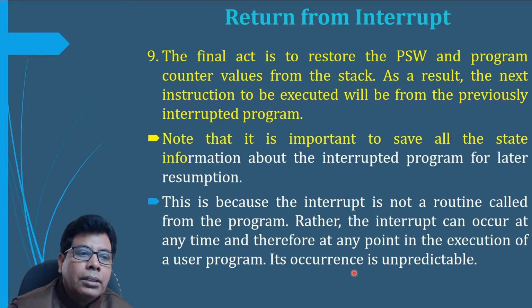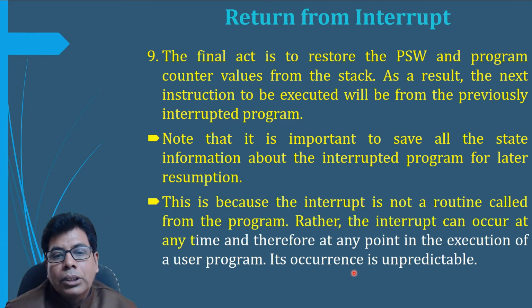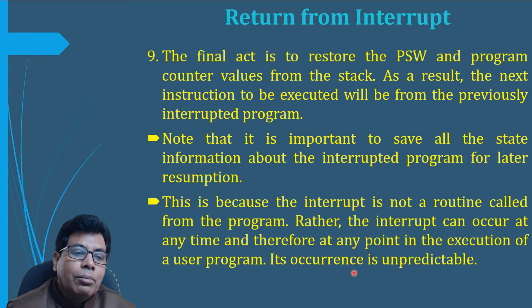Note that it is important to save all the state information about the interrupted program for the later resumption. This is because the interrupt is not a routine called from the program, rather an interrupt can occur at any time and therefore at any point in the execution of the user program. So its occurrence is unpredictable. That's why the information has to be saved properly. So this is how the interrupt processing will be done.